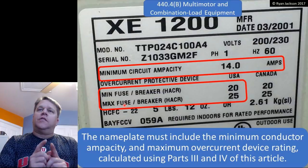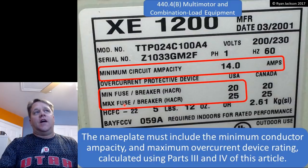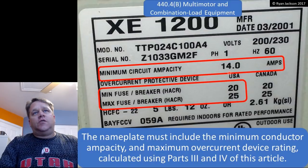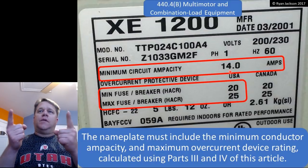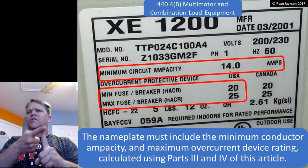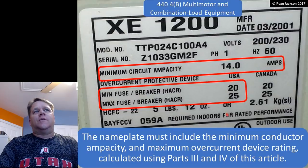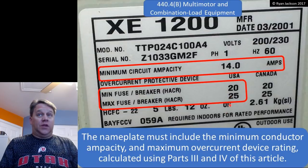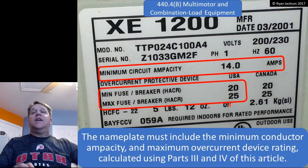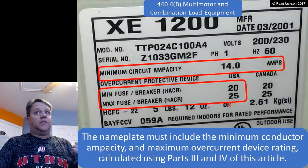A ground fault and a short circuit, right? Taking two wires, jamming them together. If I have 14 gauge wire, and I take the black and the white, and I smack them together, I have a short circuit, right? 240 volts, line to line. If I have a short circuit, is that going to trip the 25 amp breaker? Absolutely. If it's not my lucky day, it will blow the 400 amp main. It will absolutely trip the 25 amp breaker.